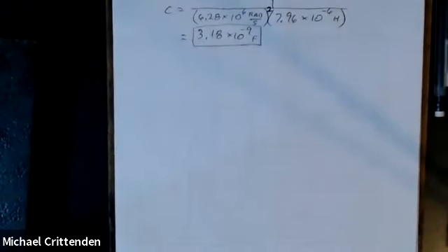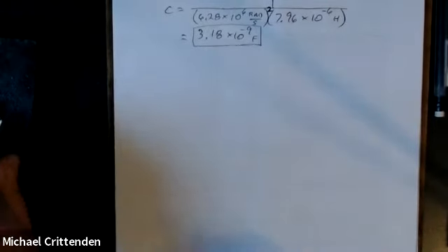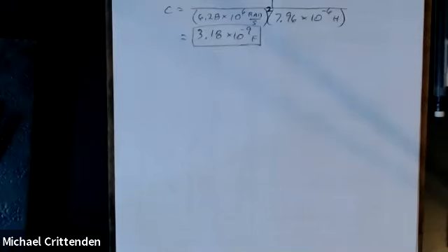So, an application where you'd want a significant amount of amps is to weld with, because of I squared R heating, you want to melt the metal. Plus, you want the voltage fairly low, to reduce the risk of electrocuting the person who's doing the welding.